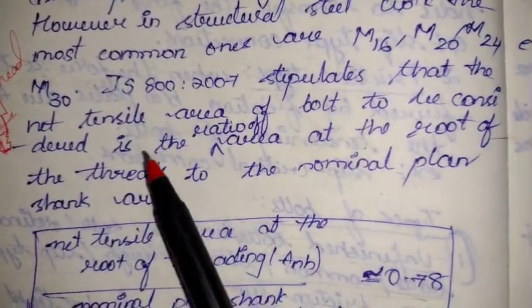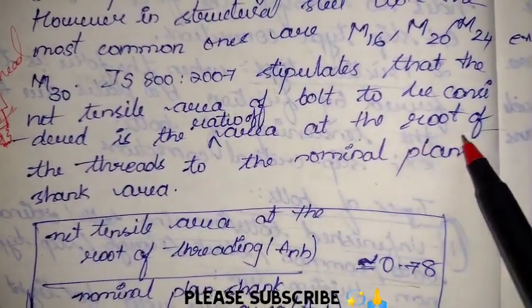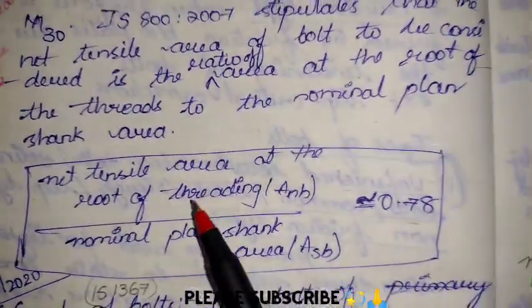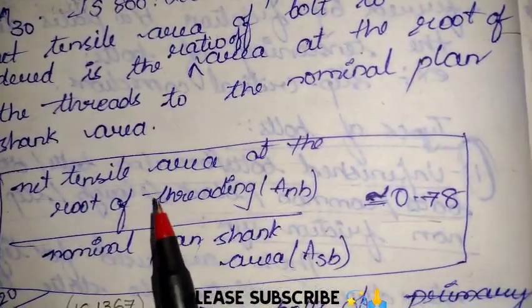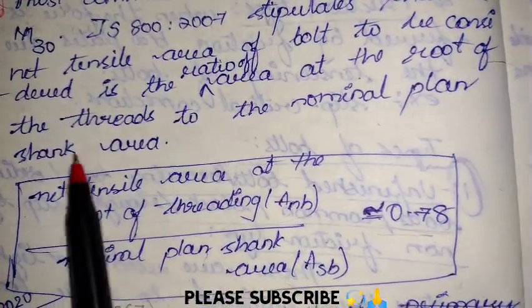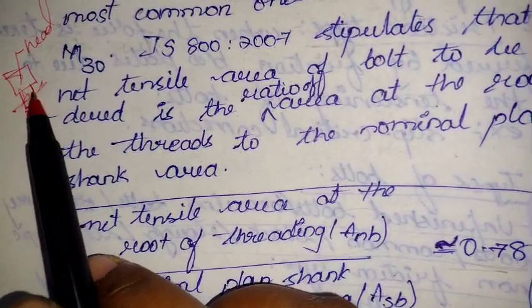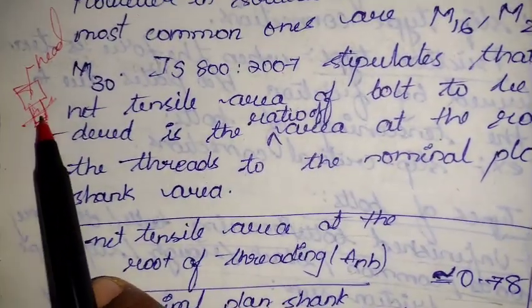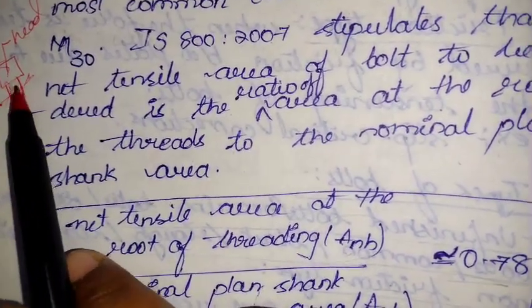It stipulates that the net tensile area of the bolt to be considered is the ratio of the area at the root of the threads to the nominal plain shank area. So depending upon the IS codal provisions, this is the recommendation. I told you this is the shank diameter, but we also have the threaded diameter. So for this one area is there, and this is the other area. The threaded area, and this is the shank area.